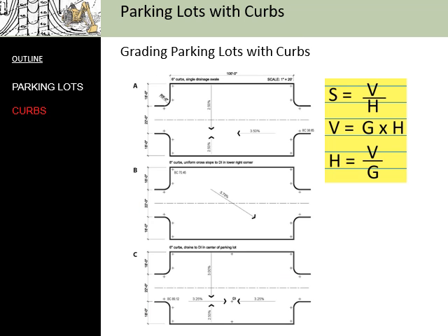For your next assignment, we're going to ask you to grade 3 different parking lots. And we're not asking you to make any design decisions here. We have made all of these for you. We have decided what the slopes are, what the elevations are, how tall the curbs are. Your job is to determine what the spot elevations are. We've even shown you where those need to be. Determine where the contours are going to be, and then draw this up with correct spot elevations and contours properly labeled.